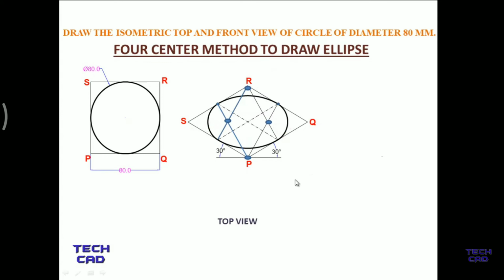Okay, so now I'm going to make a front view. In the front view, I know that, make a reference line over here, make a point on this one and make a line PQ exactly at an angle of 30 degrees. Now instead of the 30 degree line, this PS, I make this PS line exactly orthogonal or 90 degrees to the reference line. Now complete your rectangle accordingly. So this is PS. So now I'm going to make SR. So this is SR.